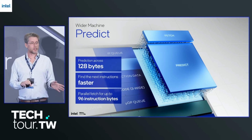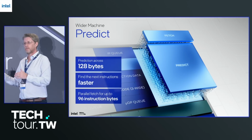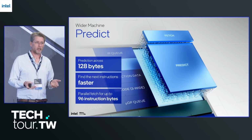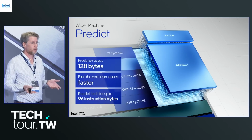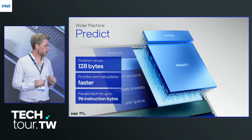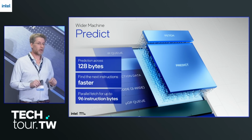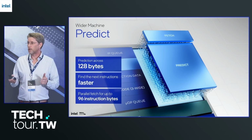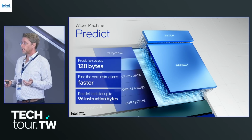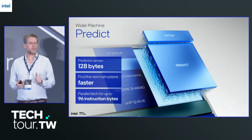It's not 96 instructions, it's 96 bytes that can produce instructions. Remember, x86 is a variable length instruction ISA, so it could be 96, it could be fewer than that. We can grab 96 bytes every cycle and load that into some buffering before we send it to our decoders. Those are 50% deeper as well.